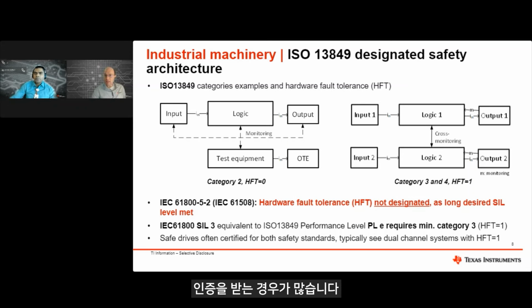So let's have a look at options to realize safe torque off, or in other words, disable torque generating power to the motor. With mechanical relays, this can be achieved by either disconnecting the AC mains input to the inverter, or we can disconnect the output of the inverter to the motor. Today's drives, however, typically use electronic solutions, as shown with items number 3, 4, and 5. For example, we can remove the power supply from the gate driver, or we can disable the PWM input to the gate driver, so the power switch will turn off and no power will be generated to the motor.